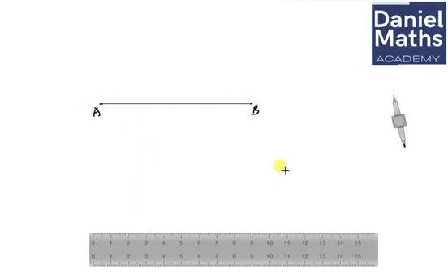So at point A now, I'm going to come back here to draw my circle. Keep this at this point, rotate this up. Now let's mark out 25. I have to draw this to 25 at this point. Once I'm done, I'm going to move this over to here, put my pin here, and make my circle.